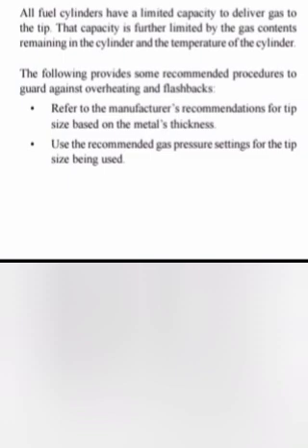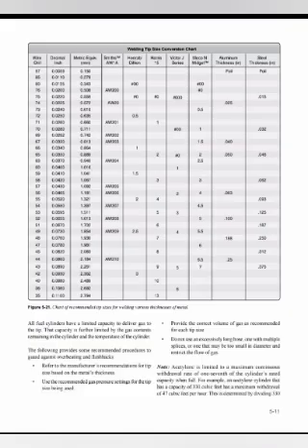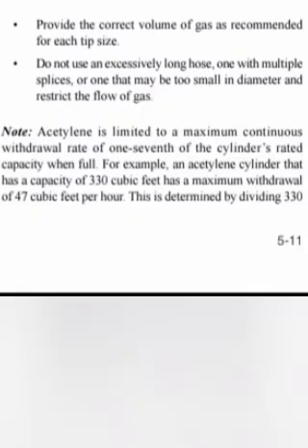The following provide some recommended procedures to guard against overheating and flashbacks. Refer to the manufacturer's recommendations for tip size based on the metal's thickness. Use the recommended gas pressure settings for the tip size being used. Provide the correct volume of gas as recommended for each tip size. Do not use an excessively long hose, one with multiple splices, or one that may be too small in diameter and restrict the flow of gas.